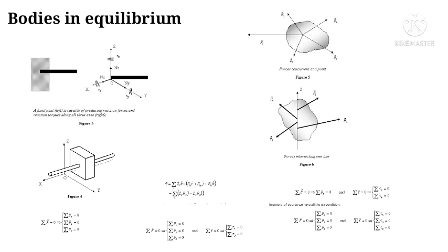If the forces are concurrent at a point O, as shown in figure 5, they all cross each other at O. Then the torque of the forces is identically 0 about O. Thus the only equilibrium conditions are that the summation of forces in the x direction is 0, in the y direction is 0, and in the z direction is 0.